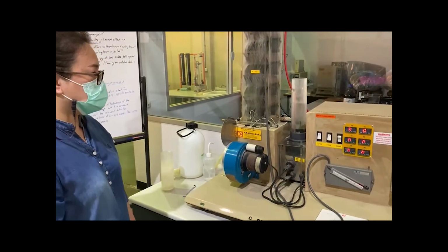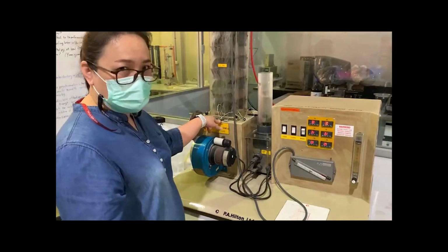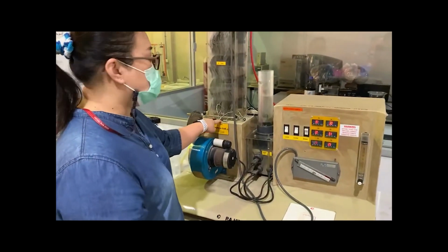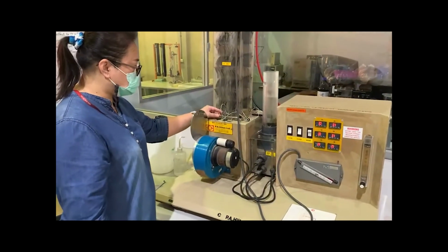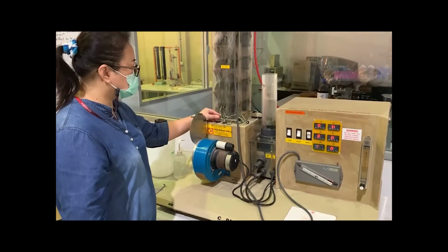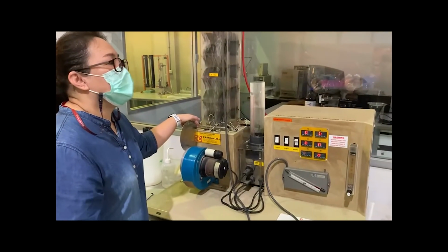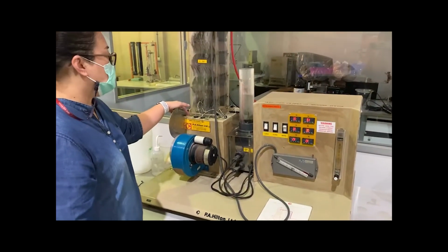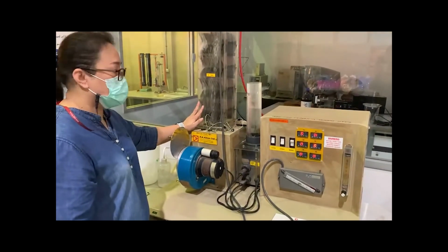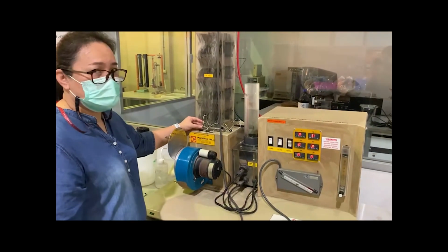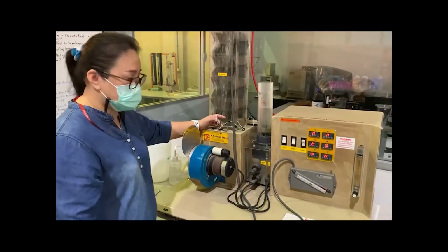Okay. Then when we turn on the main button here, we turn on our equipment. In our equipment, we have the temperature measurement equipment, thermocouples at the inlet. At the bottom part of the cooling tower, we have the thermocouples that measure the dry bulb temperature of the air inlet and the wet bulb temperature of the air inlet.